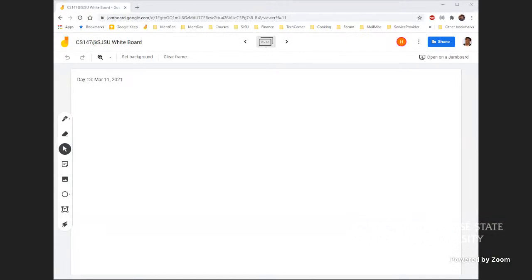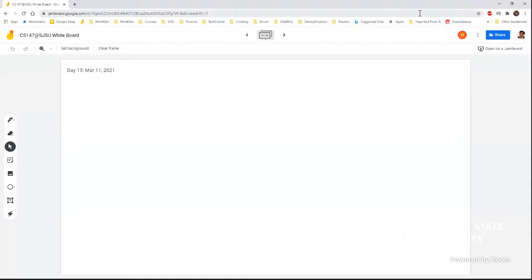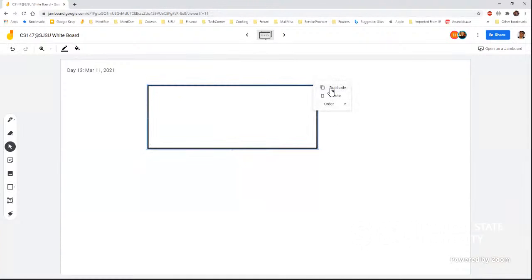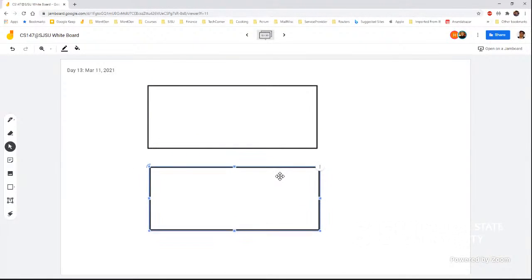Let's say your processor is a big block. One part is the data path, and the other part is the control path. What does the data path have? The data path may have several different data crunching elements. In a simple processor, like in this class, mostly the data manipulation is through the ALU. There is a register file as a storage, and there is a memory component and all this stuff.